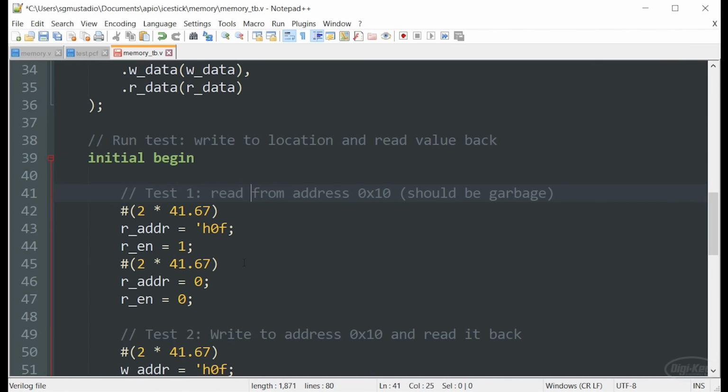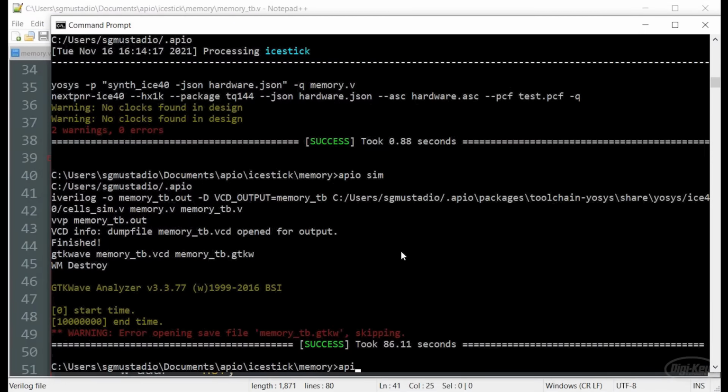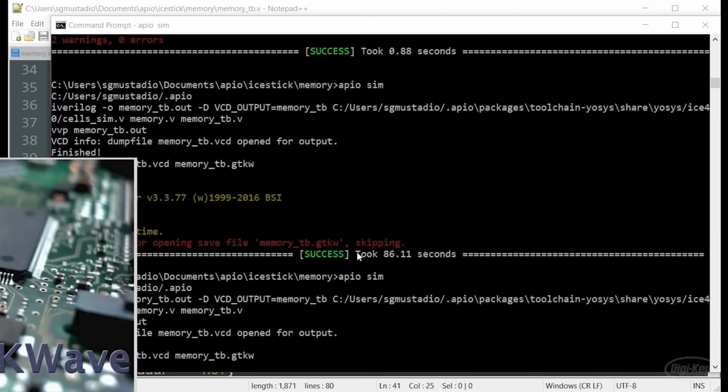If I create something that's only 4 bits wide and I try to set it as a number that's 5 bits, it's only going to use the least significant 4 bits that will fit on that bus. And this just verified that that's what's going on because 10 doesn't exist, so it wraps around and it becomes 0. Let's save this. And let's run our simulation again.